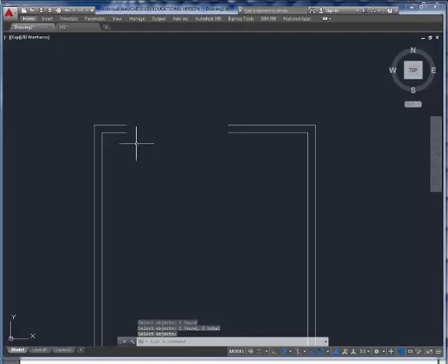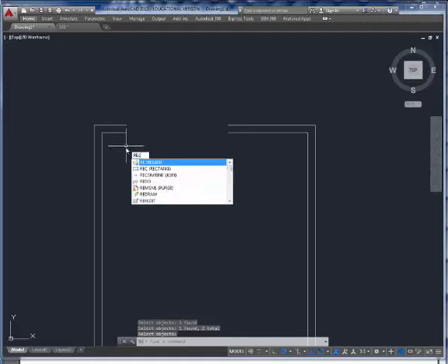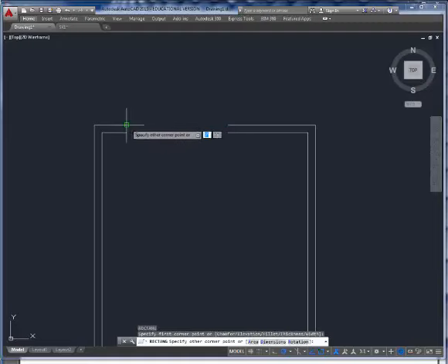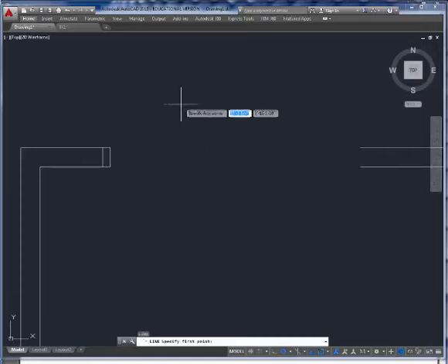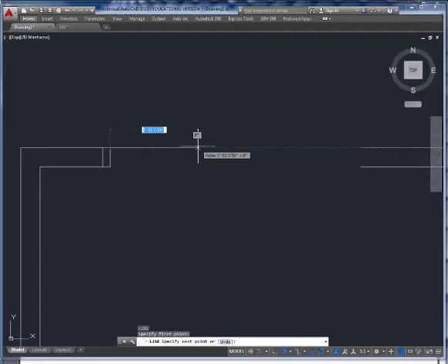There you are. I'm going to draw the first mullion, rectangle. Make your first click. I'm going to say at 2 inches on the X, comma, minus 5 inches on the Y. Those are your coordinates. I'm going to create the first window. I'm going to say line, and this is the line of your sill. We're going to learn all about pen weights and line types, and that is when we will be able to put our exercise in layers and understand each of the parts of these windows.